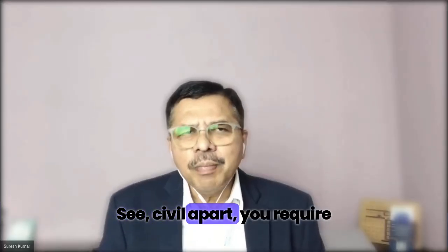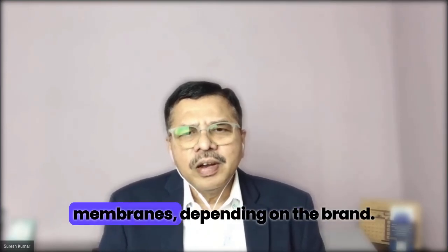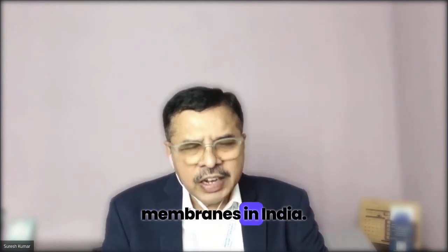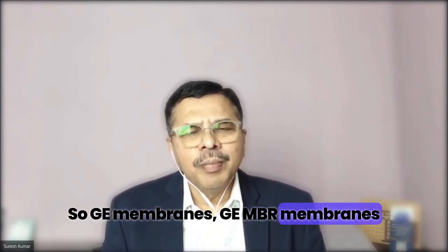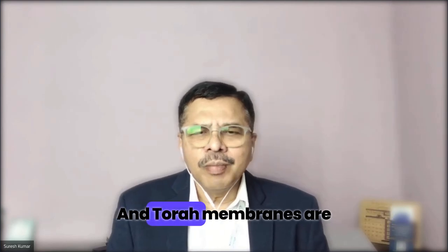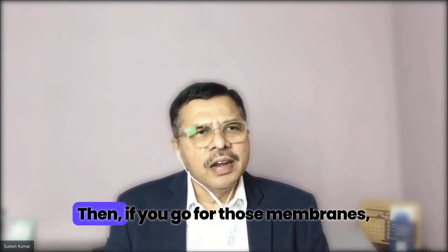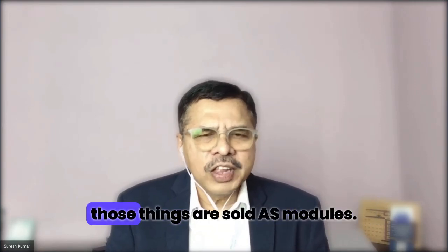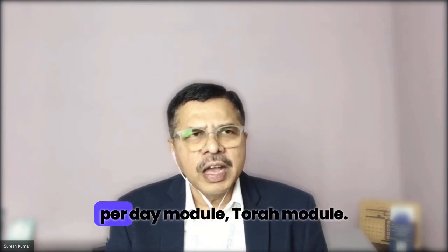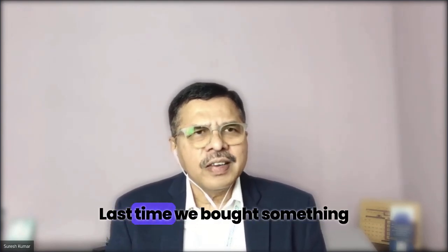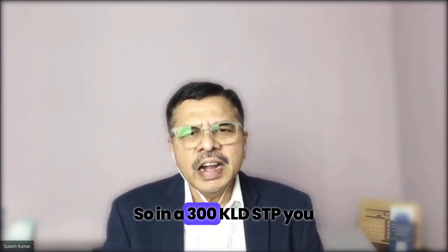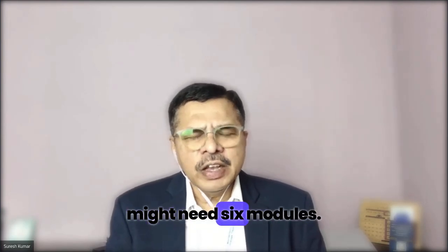See, civil apart, you require membranes, depending on the brand. Now, Genpack or GE makes membranes in India. So GE MBR membranes are relatively cheaper. Toray makes them in Japan or Indonesia, and Toray membranes are slightly more expensive. Those membranes are sold as modules. A 50 KLD module, a 50,000 liters per day Toray module, last time we bought for something like 11 lakhs each. So in a 300 KLD STP, you might need 6 modules.